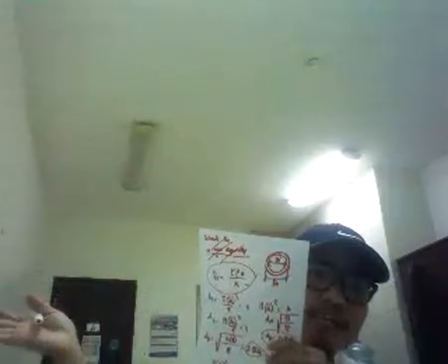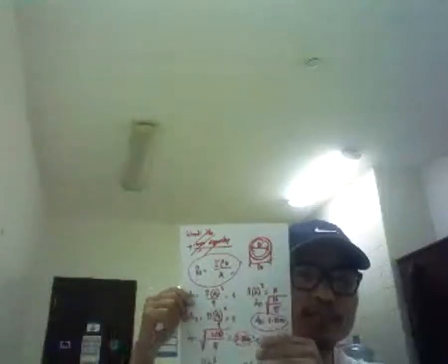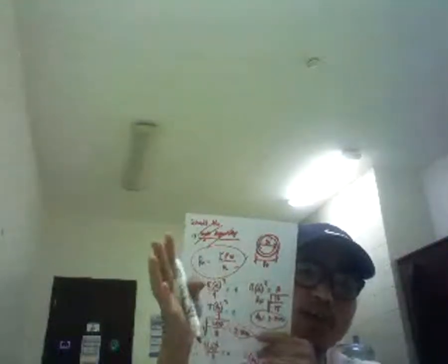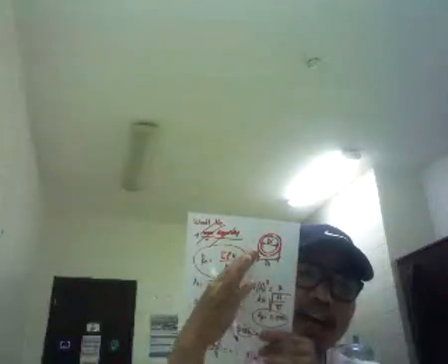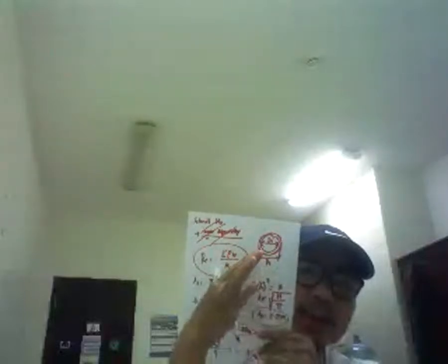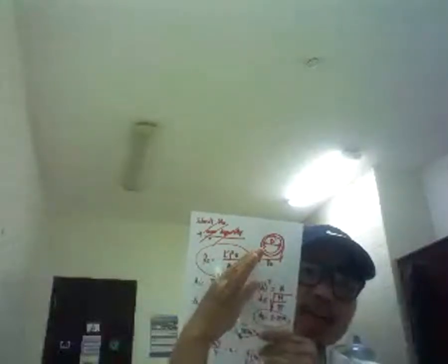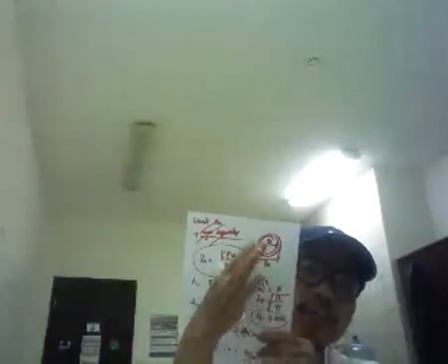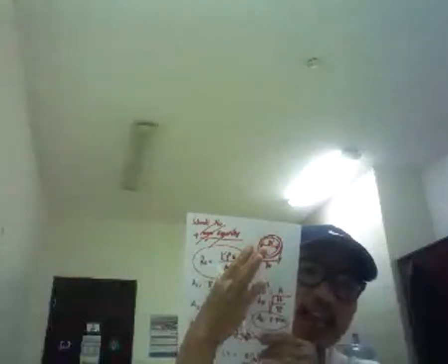So we are focusing on the inside diameter because that is where the fluid will go. It's not the outside diameter, or else the water will escape. You understand my point? The inner diameter will be considered, not the outside diameter, because in the inside diameter the water will flow. The outside or external diameter of the pipe is bigger than the internal diameter. Now, in Reynolds number, we use the inner diameter of the pipe, the inside diameter. That's what we are looking for, not the outside.